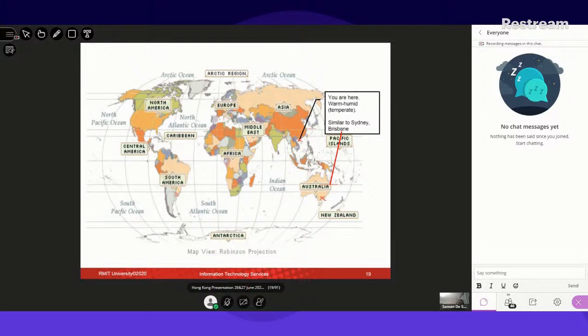So basically, the point which we are raising here is, if you are designing a particular building or a house, you have to think about the environment, the climatic condition of that place, and then orient the building in such a way that the energy consumption is lesser. If you don't give proper respect for the orientation of the building, what will happen is, which side should I provide my large windows, which side is the warmer side of my house, which is the cooler side of my house.